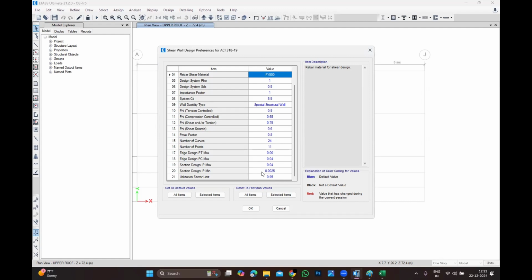Factor of safety. People are thinking, I'm keeping a bit conservative. No, there's no conservative design. It's over design. Knowingly, you're doing over design, because you do have many factors. The 500 MPa you're talking about in steel, actually it is not 500. It is much more than that. And on top of it, you do have the factor of safety, the load combination. You're not even designing for service combination. You're designing entirely by ultimate combination. So don't keep any factor of safety on top of it.